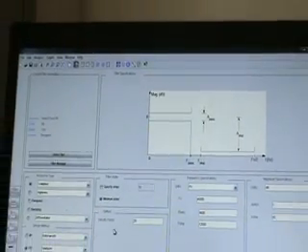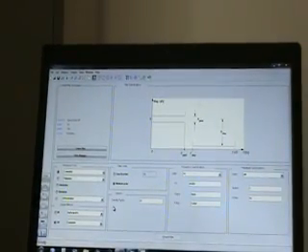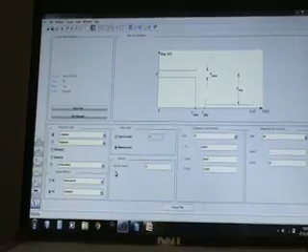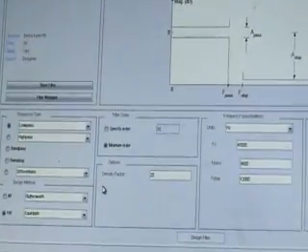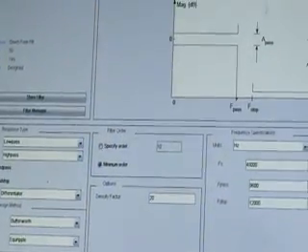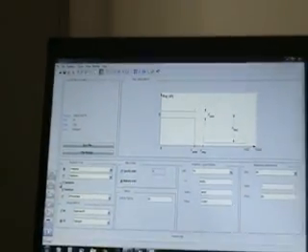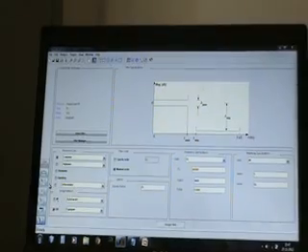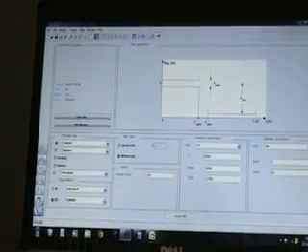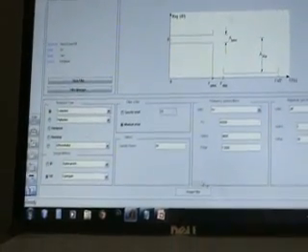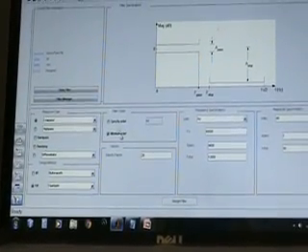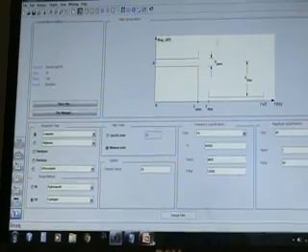And coming to the design panel, at the bottom is where you define your filter specifications. It controls what is displayed in the other two regions. Other panels can be displayed in the lower half by using sidebar buttons. We'll be seeing all these buttons in the coming video. Now next we'll see how to design a filter.